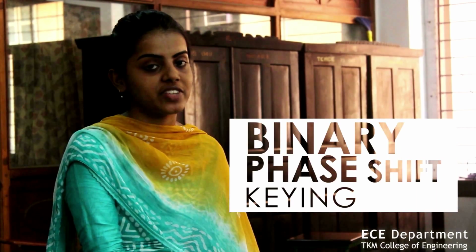Now coming to BPSK or binary phase shift keying, here the phase of the carrier signal is varied according to the amplitude of the information signal, which is in the form of ones and zeros. Here also the same components as in the case of BASK are used, but the 741 here acts as an inverting amplifier. When the clock is 1, we get a signal of particular phase, and when the clock is 0, we get a signal which is 180 degrees out of phase. The inverting amplifier provides this 180 degree phase shift.